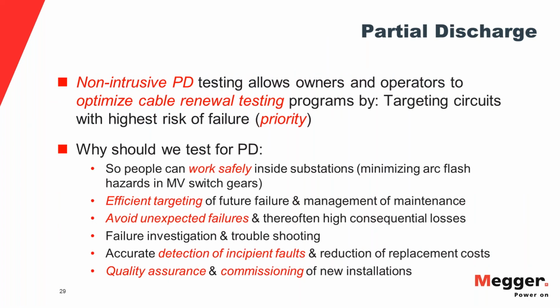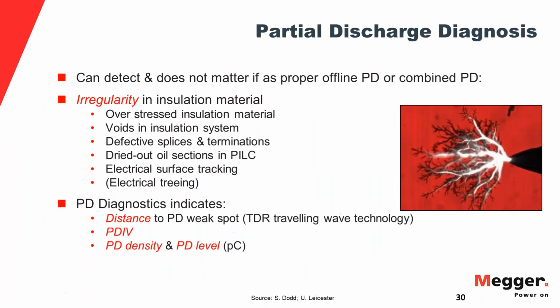So the best way to actually see this is partial discharge testing, which is a non-intrusive, or minimally intrusive, kind of test. And typically when you use a non-continuous waveform, as we will talk about in a second, it's also considered non-destructive. At the end of the day, you want to find out which circuits to prioritize. We talked about this, and this is just a little bit more elaborate. You get the presentation, so we don't have to talk about it here. You can read up on these things.